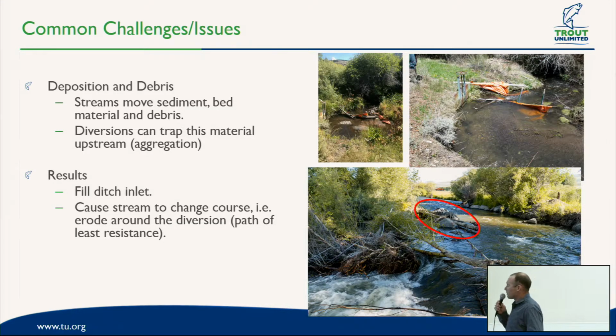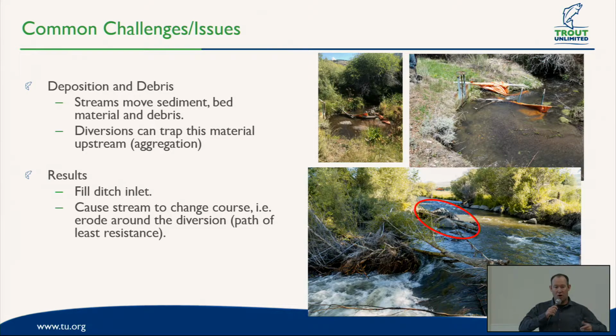With these common challenges, I'm going to refer to dams essentially, because that's what's used up here quite a bit, whether it be a wing dam or a full channel structure or rocks. When you do place something in the stream, you've got a range of flows. Streams naturally move material, debris, bed material, and it can deposit upstream of your diversion.